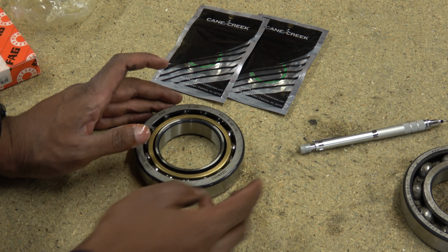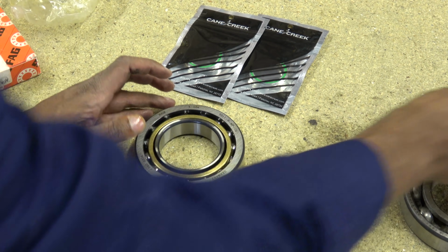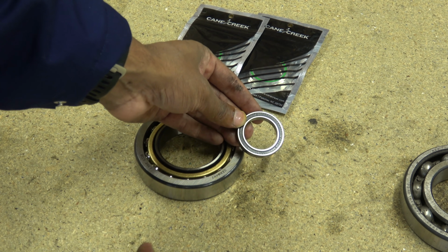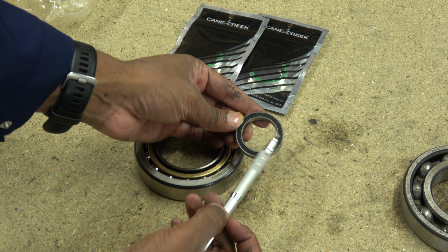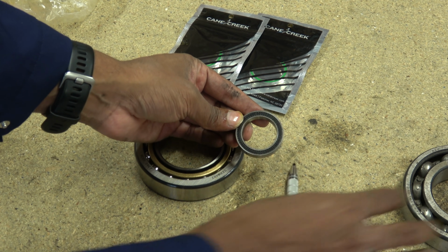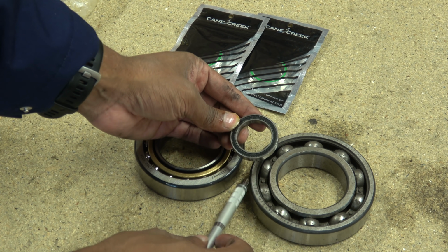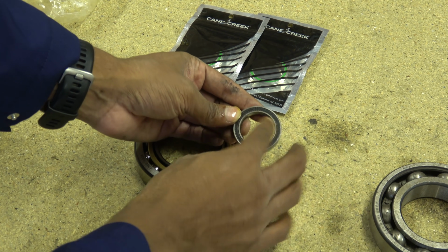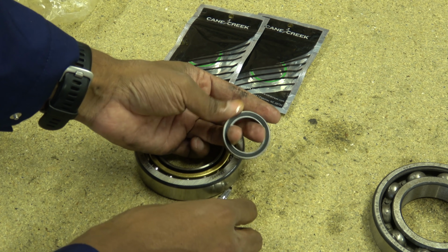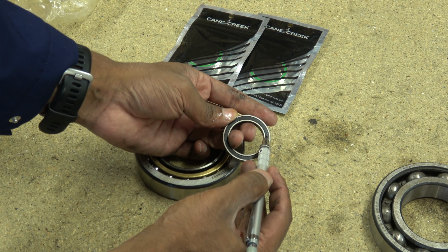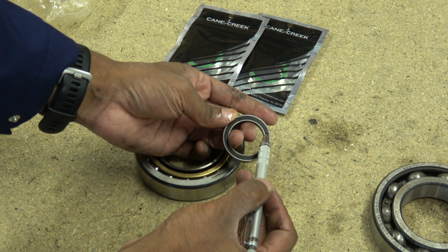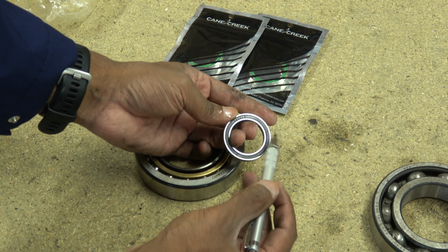So just to give you a quick overview of some of the terminology that we go through. If I use the smaller bearing, just to start off with, this black thing is the seal. Seals come in generally 3 types. So there's this one, which has no seal. This one, which is a non-contact seal, so it spins quite well. And the next type is a full contact seal, so the black bit touches both the inner and the outer.